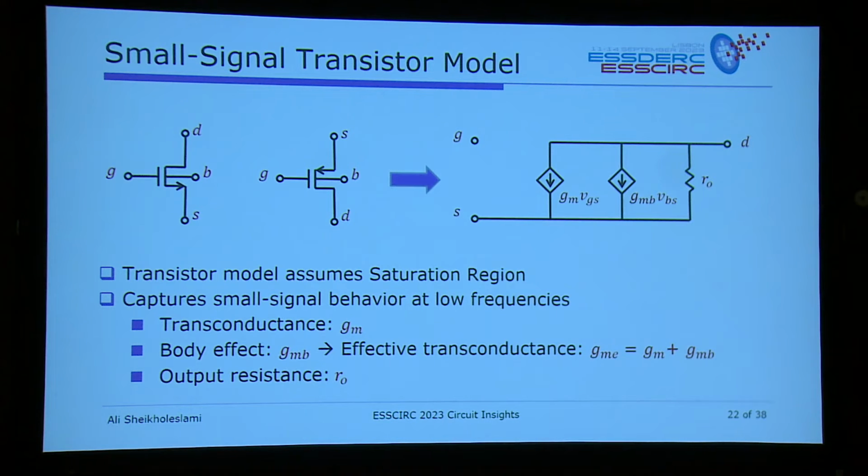And now let's see what we can do with this and how we can marry this to the Thevenin-Norton equivalent circuit that we have seen. First thing I want to tell you is that this is applicable to the Norton and Thevenin equivalent circuit because these are, again, dependent sources, but they're linear and you have a resistor. So there is a Thevenin-Norton equivalent circuit for this.